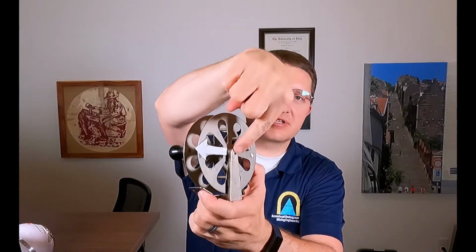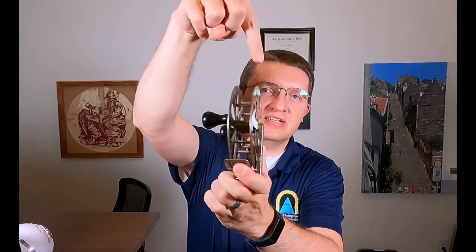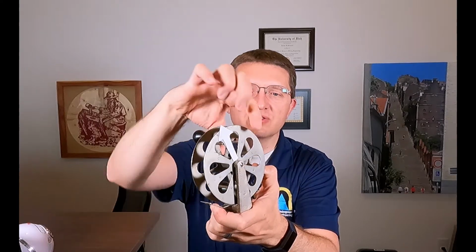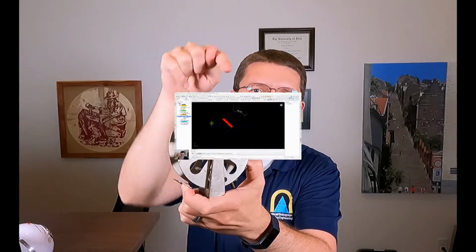So you have to first click on this point on this side, then you have to click on this point on the other side, and then punch in a number, and it's going to rotate along that axis. So you could draw it this way, you could draw it this way, you could draw it that way, and you're just going to rotate it along this axis. The important part is that you define where this axis is with 2 different points.